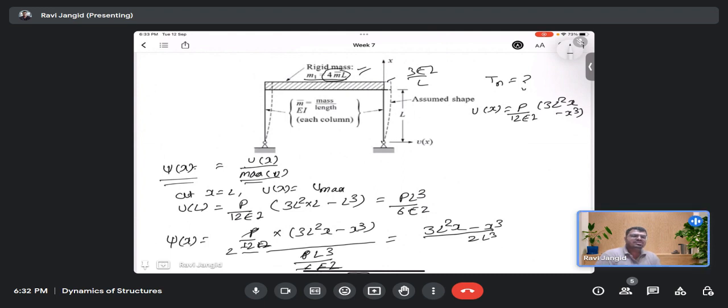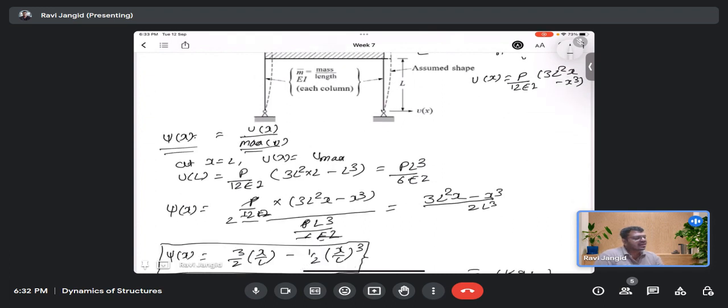In the lecture, you are considering only, let us suppose, a cantilever, and some mass is given to you, and some section property EA is given to you. So you calculate M equivalent, K equivalent, and directly calculate frequency as K equivalent by M equivalent.